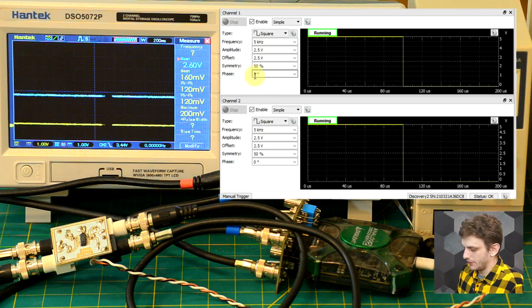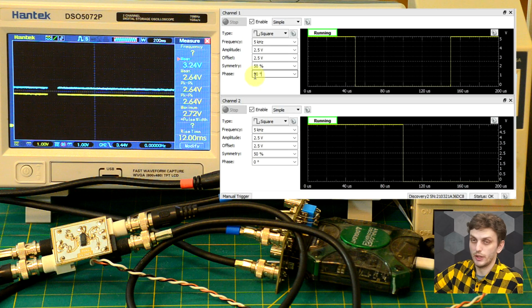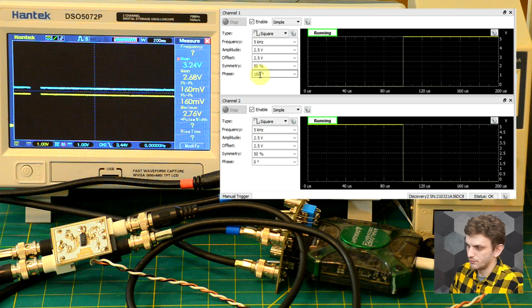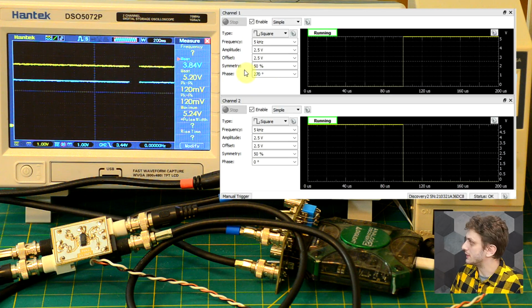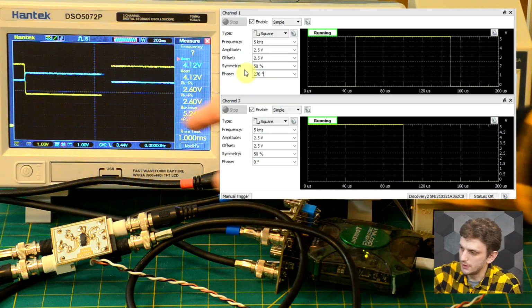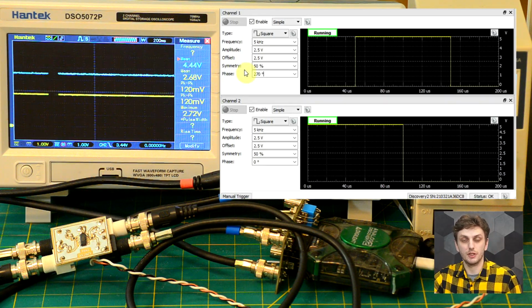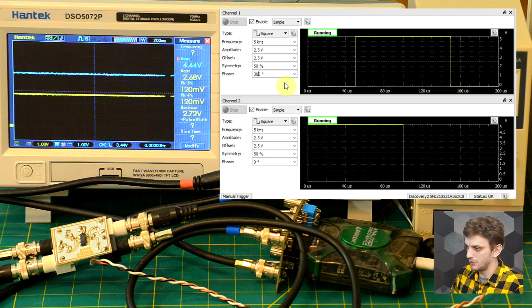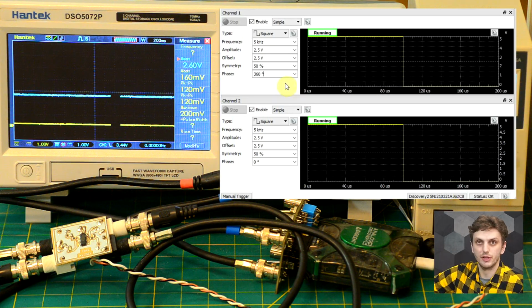So now if we start to increase the phase difference, say we go to 90, we see both outputs go to higher values, as expected. We can go even higher to 180. Again, both outputs increase. Now if we go to 270, we can see that the type 1 phase detector dropped in output. So we see this behavior that after 180 degrees the output starts to decrease rather than continue increasing, whereas the type 2 still increases. And if we go to 360, well, we're back where we started. So again, 0 phase degrees, we're at the reference.